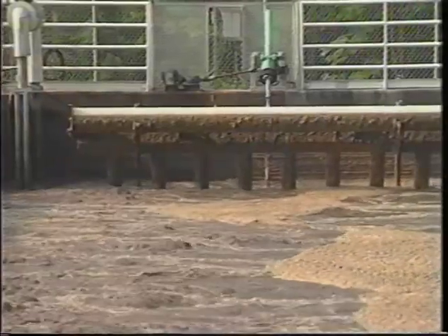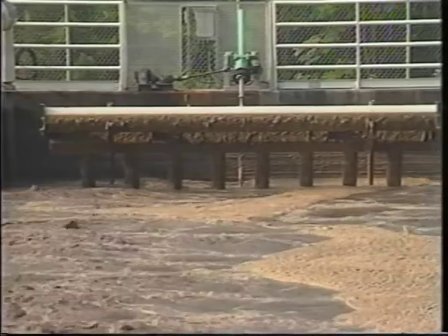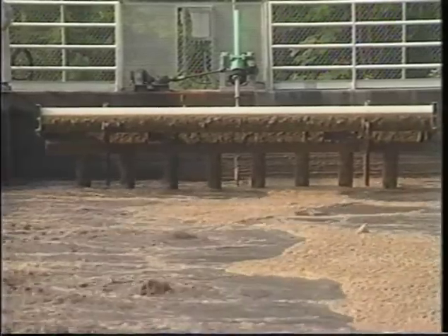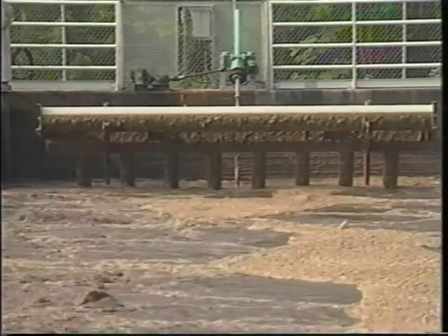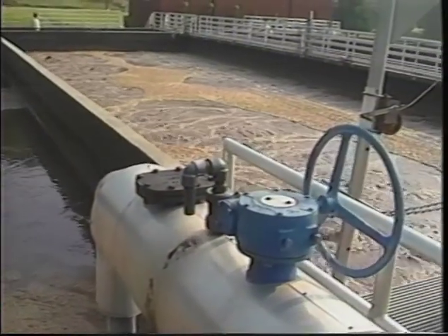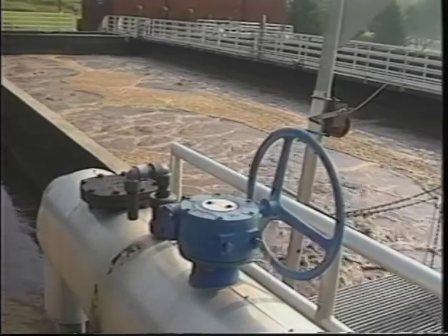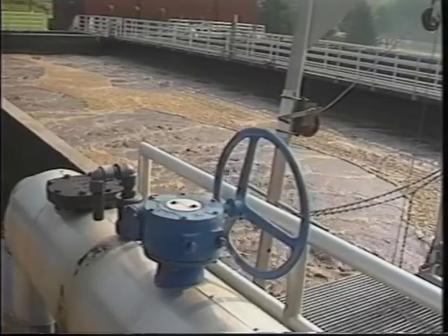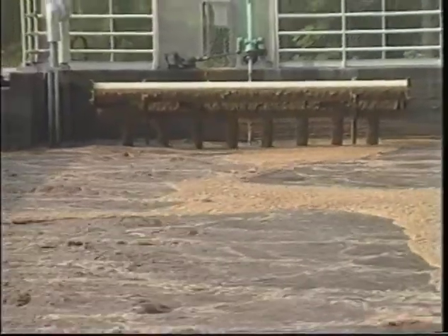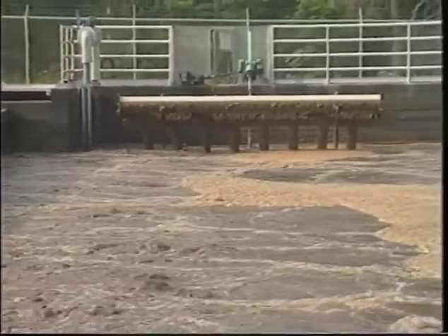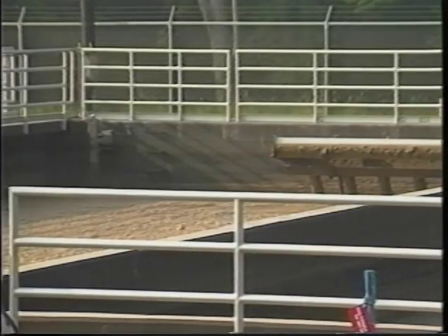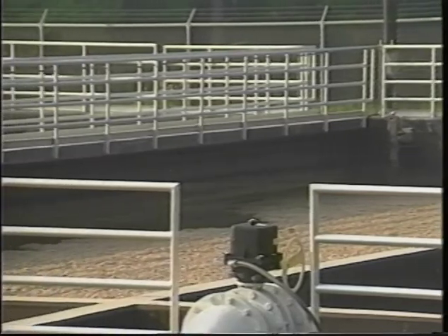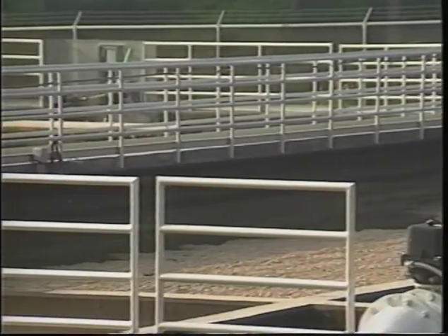The filling mode, where the raw wastewater enters the aeration tank. In this mode, the contents of the tank may be mixed and aerated as well. The mixing and aeration mode, when the tank is full and the microorganisms feed on the pollutants in the water. In this mode, no wastewater is entering or exiting the aeration tank. The settling mode, where the tank essentially becomes a clarifier. No mixing, aeration, or filling takes place.